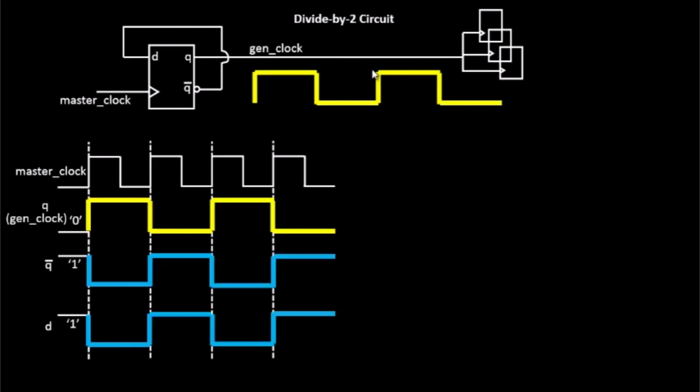It's not a dynamic timing analysis. So basically whatever waveform you achieve at this point of time has to be defined somewhere so that the further analysis will be done based on this waveform. Had it been a dynamic circuit, this waveform would have been automatically derived at this point. But since it's a static timing analysis tool, for this gen clock, after understanding the circuitry behavior based on these graphs, you need to get this graph at the output of gen clock, and the further circuit has to be analyzed with respect to this waveform.